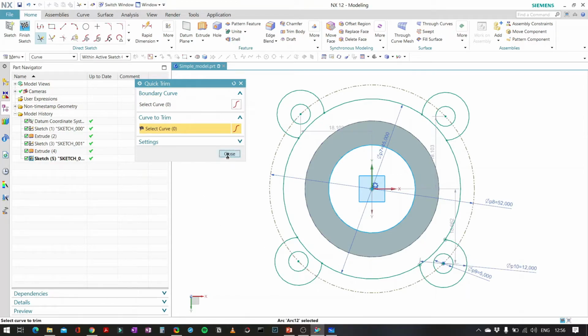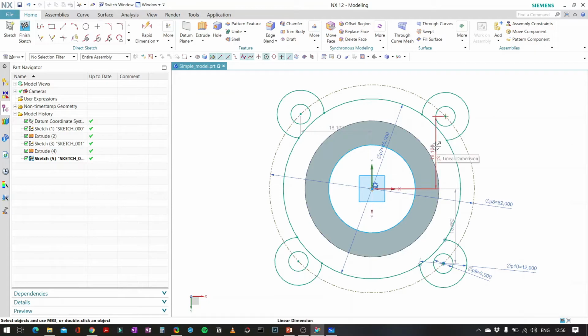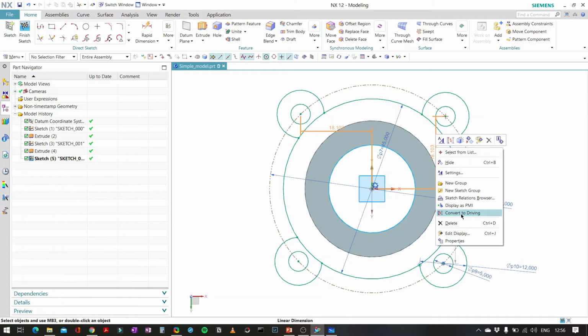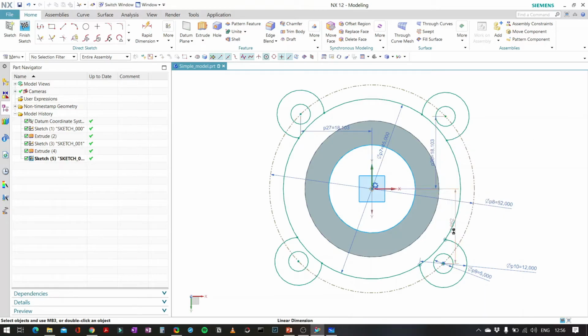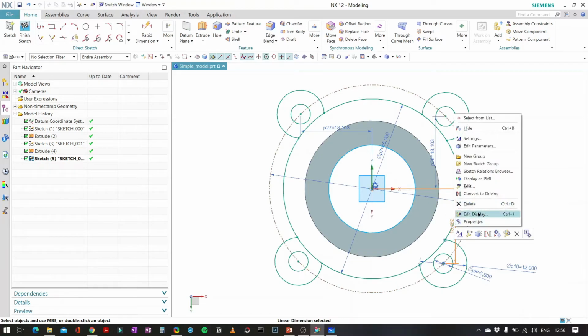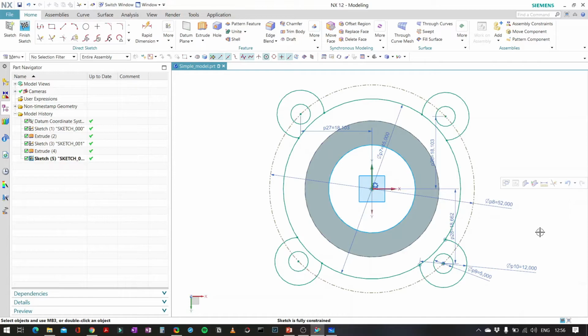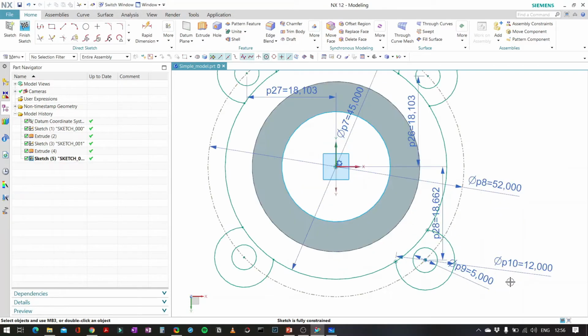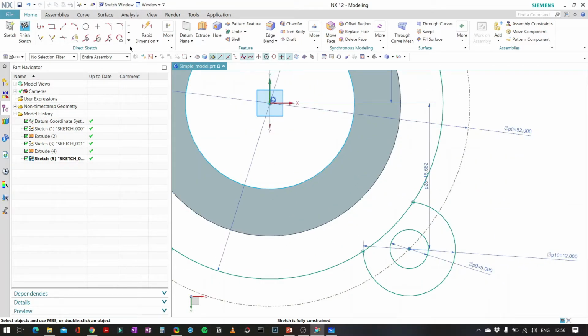We'll click on it. If you see, all the other 4 things also got patterned out, and we just make sure that we have auto dimensions. What we have got, we will make sure that those are converted into driving dimensions, so that they will not get changed. Now what will come here is there is a fillet option.